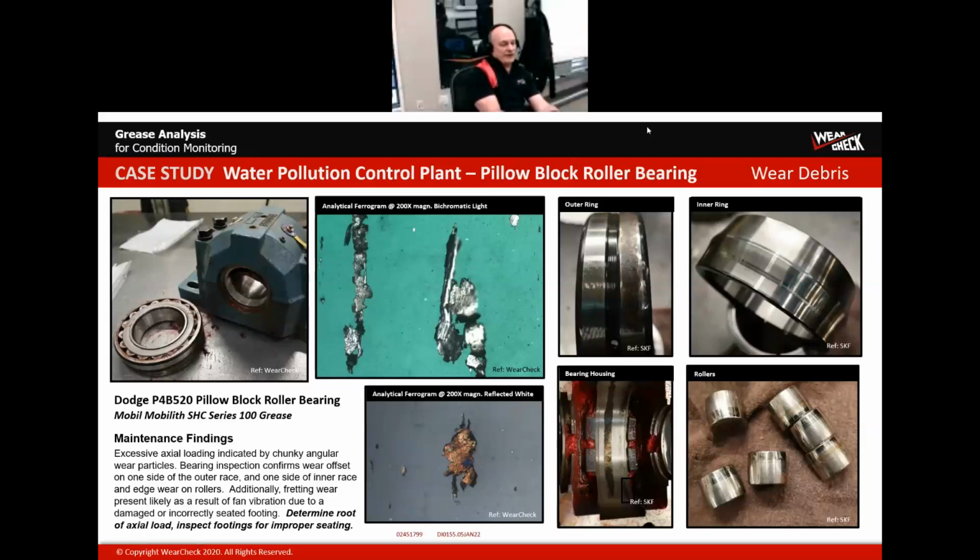But the wear particles that we were picking up were not really an indication that the contaminant was a significant issue. So what I would expect to see in that case was more cutting wear particles. What was really dramatic is if you look in this center photomicrograph, the one with the green background from the filter, some of these particles were of extreme concern. So again, in ferrography, when you begin to pick up something that's very angular, and in this case, it's quite chunky, when you look at the thickness of the particle, you recognize that there's a more critical wear mode happening.